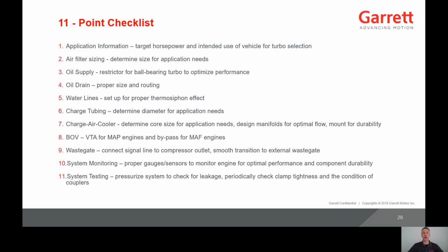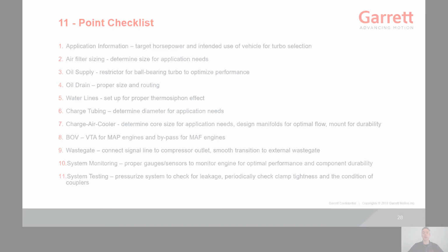System monitoring is used to optimize performance and durability. And finally, one that seems to be overlooked is system testing. Once complete, the system should be pressurized to check for leakage and periodically check clamp tightness and the condition of the couplers. This concludes the video presentation.